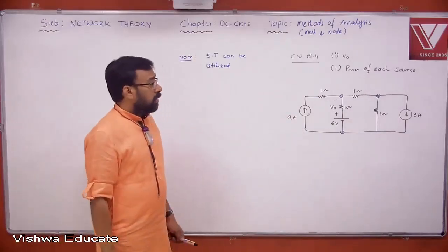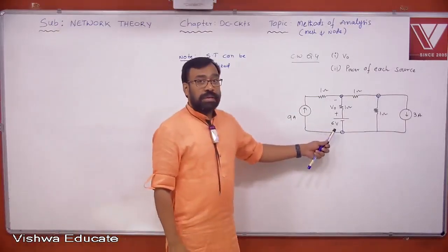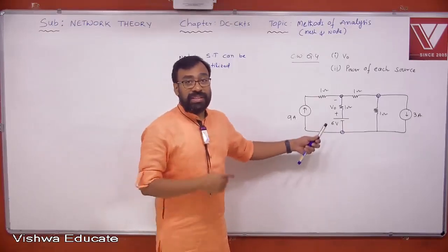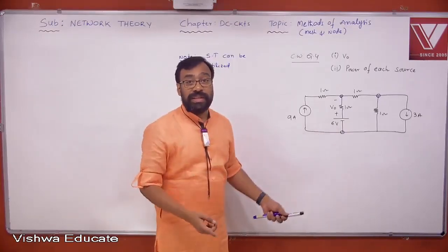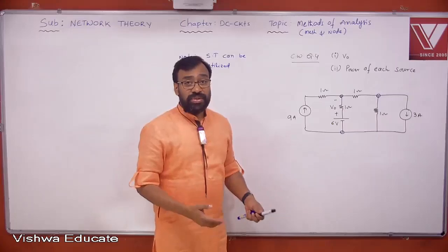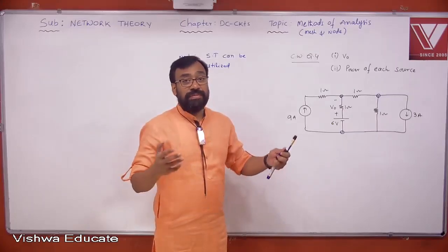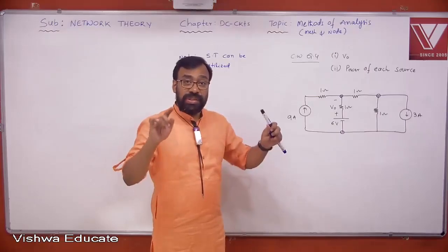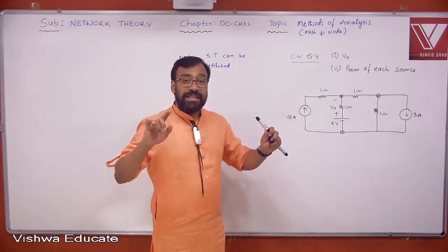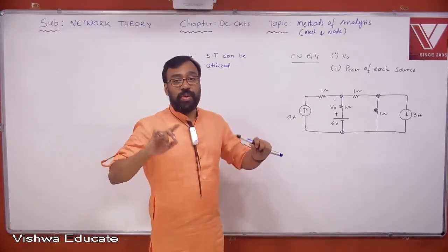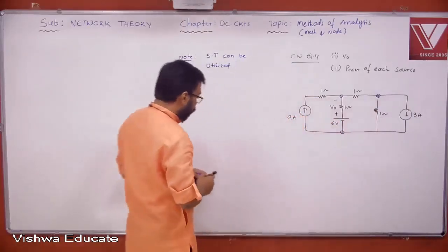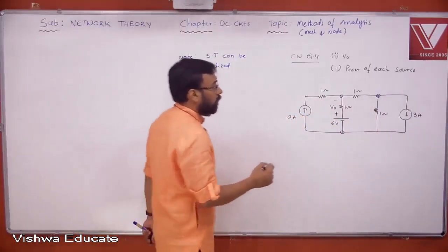Okay. What is the best method? Mesh analysis. Okay. To solve this network, you are preferring what? Node analysis. You cannot choose node analysis at the cost of more equations. That is why I am telling you here, using node analysis, I am still applying only one equation, utilizing this source transformation. Okay, look at this source transformation.